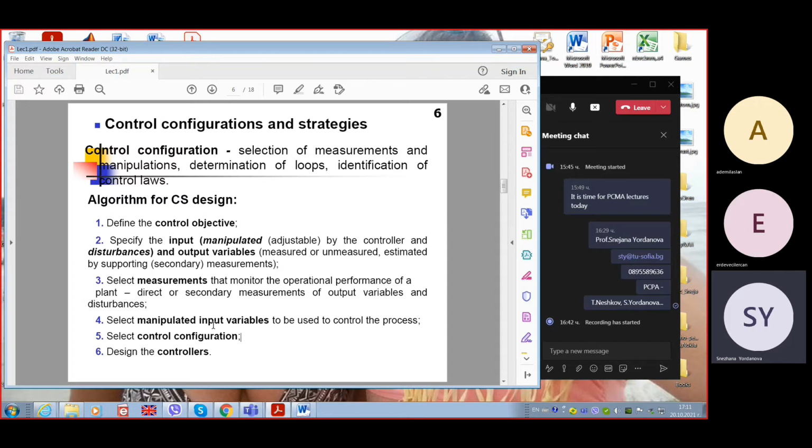So displacement of this plug vertically is related to change of the flow rate of the material that supplies the installation and allows the process to be controlled. So to reach desired level, desired temperature, what we actually control is the output of the so-called plant.